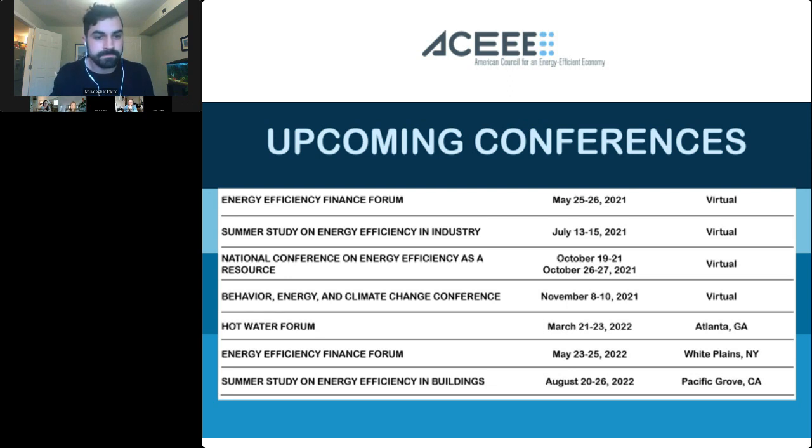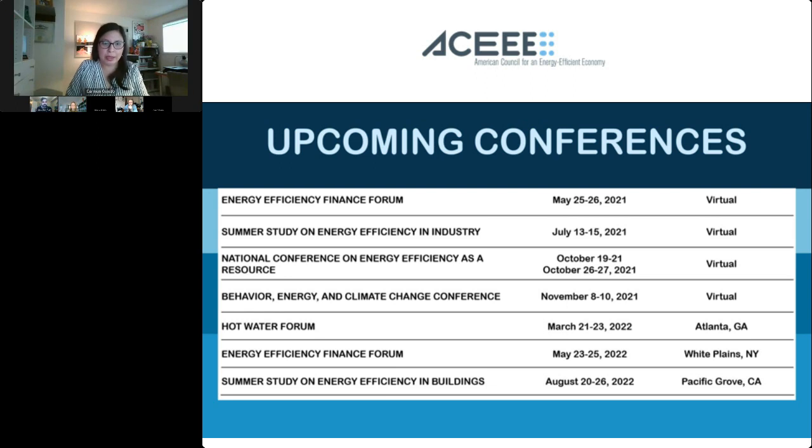I'll take this first. So ASHRAE 90.1 is a standard that can be applied internationally, and often it is. The main difference would be your climate zone, right? So the weather file that is used to run the simulations would obviously change depending on your international country that you're looking into. The peak demand, I think, is where we would want to look at your inputs for whatever your different country is. We're really focused on the United States, so those peaks are based on ASHRAE and IAPMO and ASPE research. So it's just a modeling tool. It would really just depend on the inputs and the weather file.